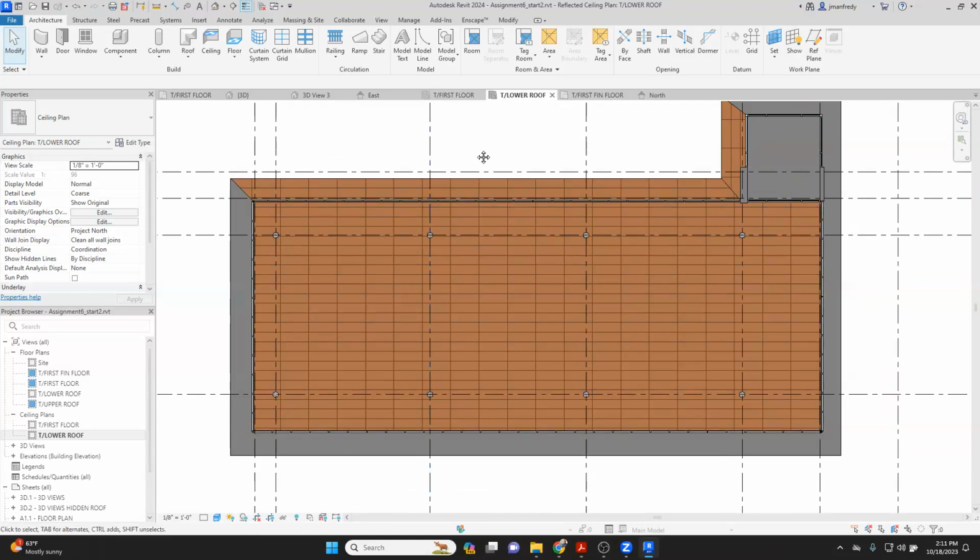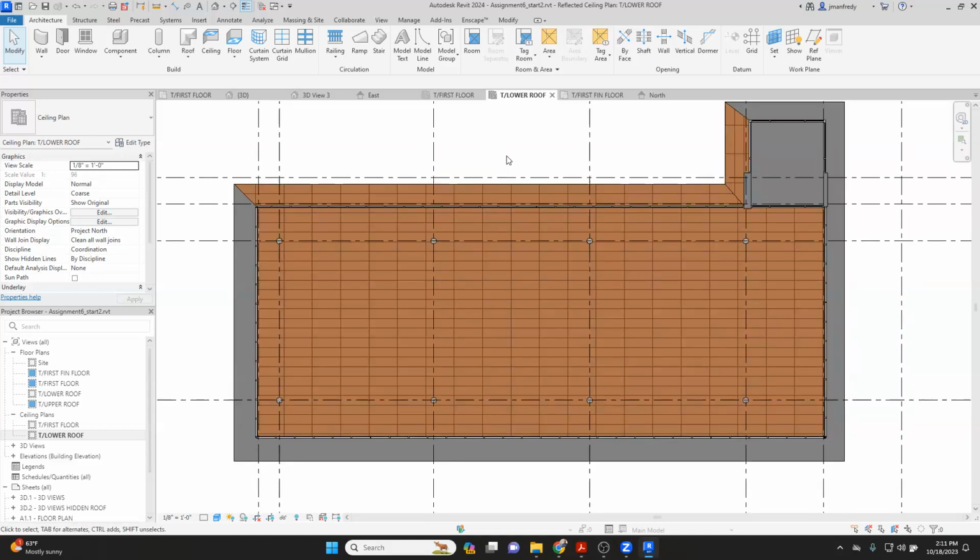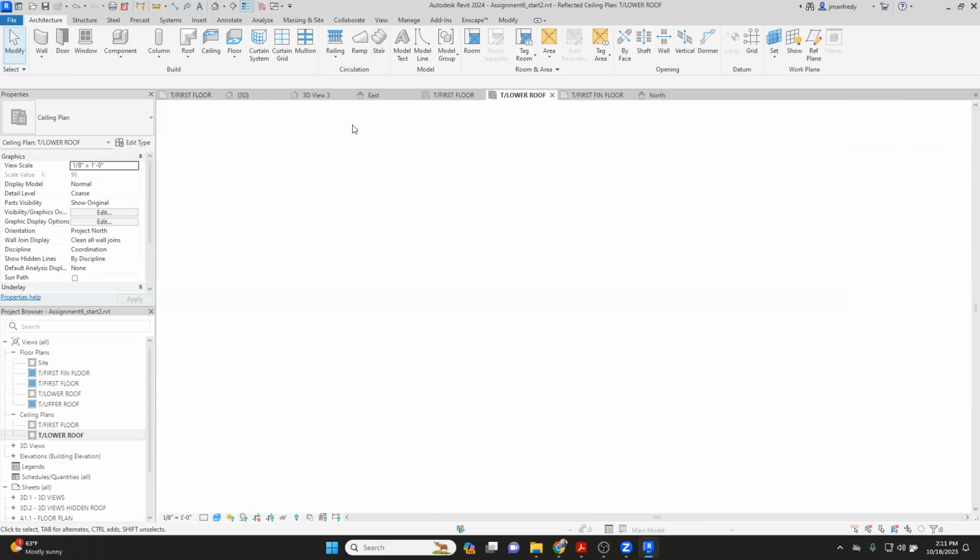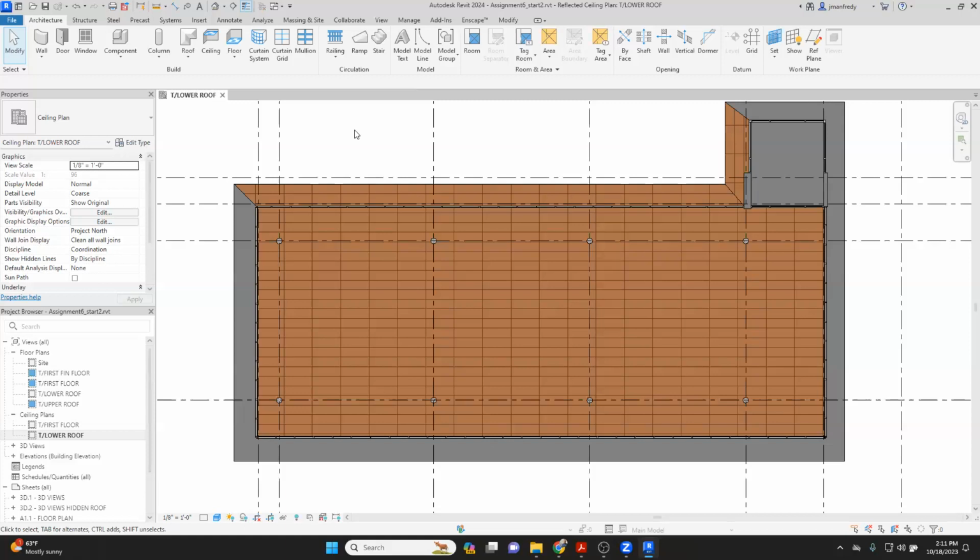So you'll complete this. I can use that design for the front entrance now. I can use that design for the security desk. I now have a new ceiling that looks this way, just like you did with the floor. Give it a new material. The material controls what it looks like. So the material needs to be whatever color you want and whatever grid pattern you want. If you don't have a grid pattern, make one.